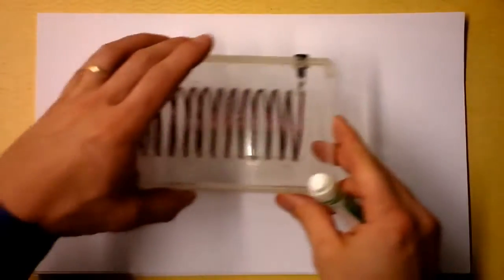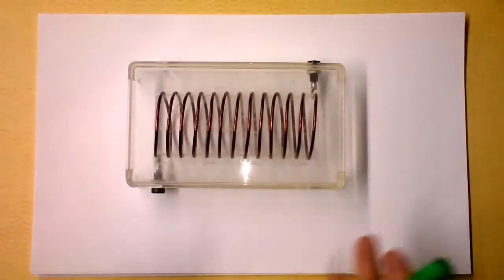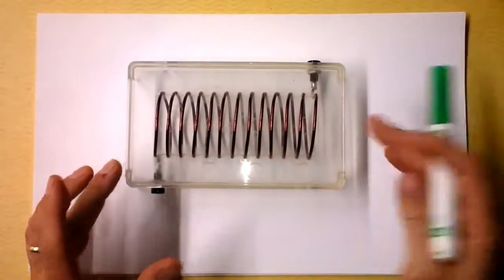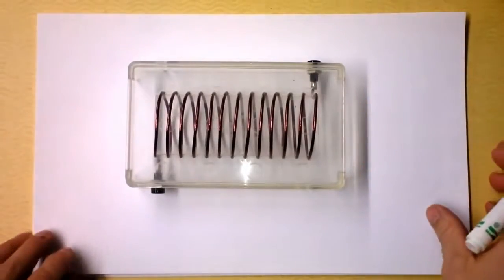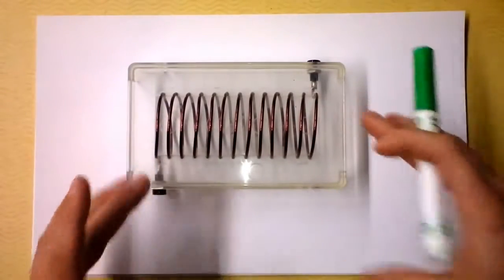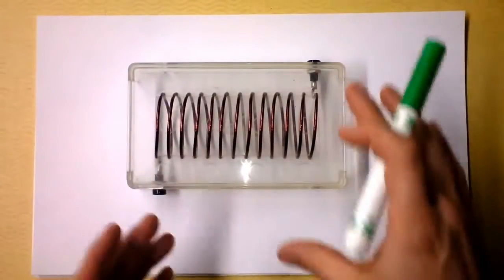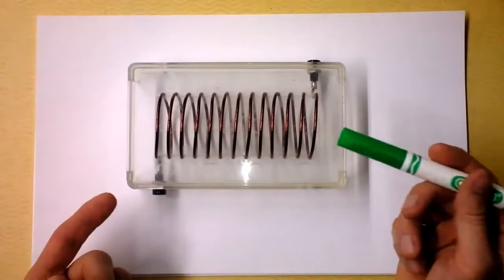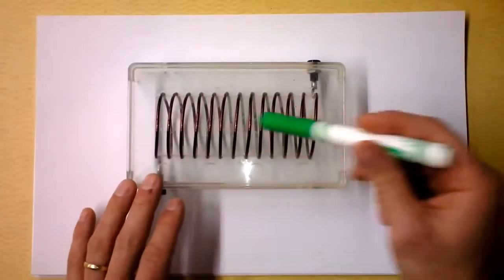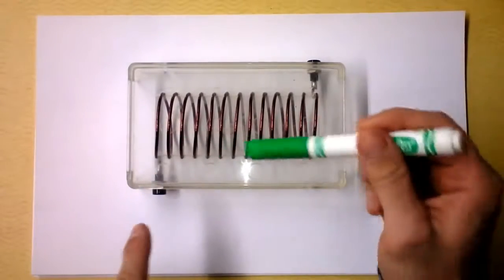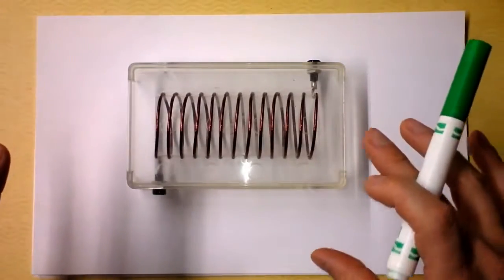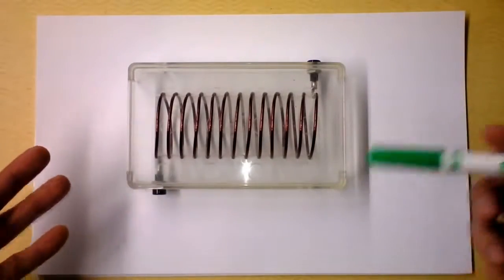You know that if I hook this inductor right here up to a battery, it will behave initially as a bad battery. It doesn't want to have any current in it, and so it rejects the current coming in and pushes it back the other way, because as the field in it changes, the inductor itself induces a voltage in the other direction that tries to not let the current within itself change, so that the flux through it doesn't change.